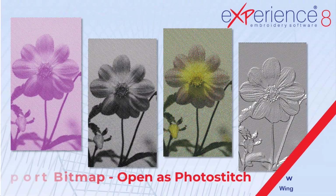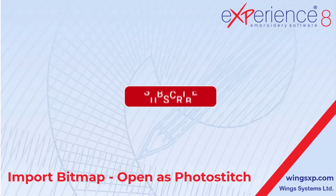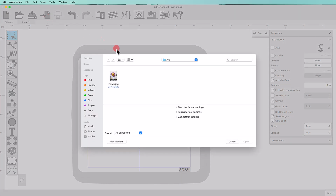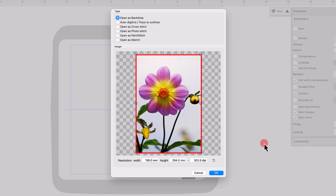In this video, we will continue importing bitmap images and we will show you how to convert one into a PhotoStitch design. The procedure is simple. First, use the From File icon to locate any image you like. Find the bitmap image you want and open it.